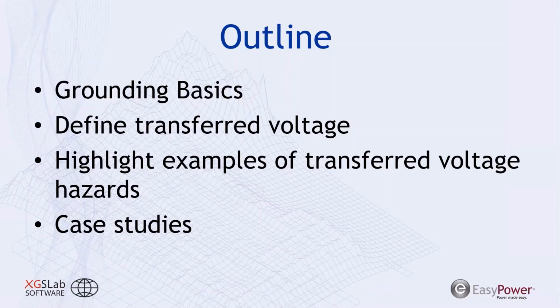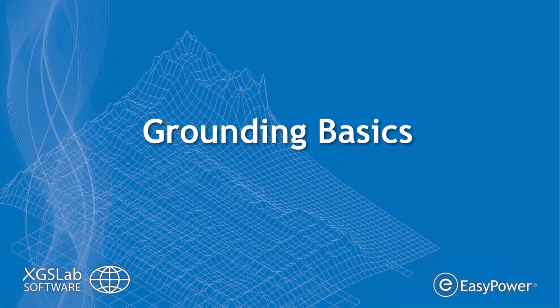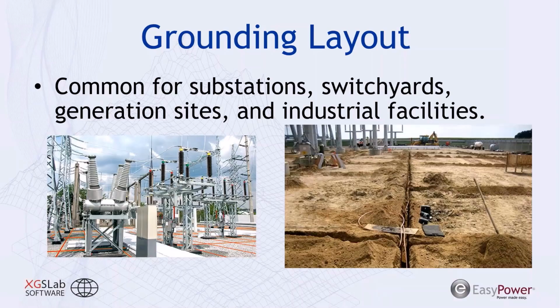Of course, when you have these types of studies, all the information that you can get is very valuable. Soil resistivity data, fault information, actual measurements, if you can, of any transfer voltages is very valuable so that you can bring that into your analysis world and develop designs more accurately. So with that, let's go ahead and jump into some of the basics of grounding system analysis.